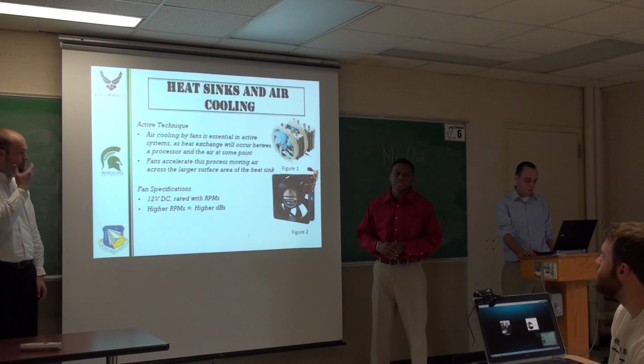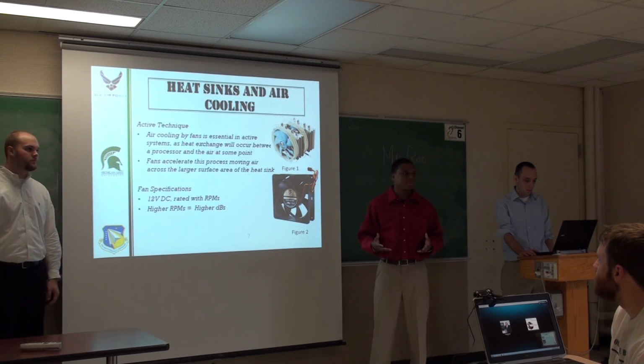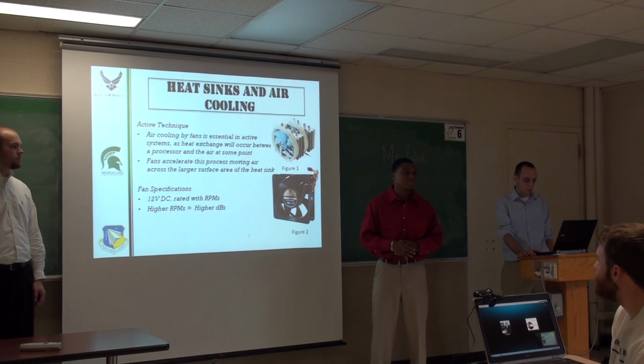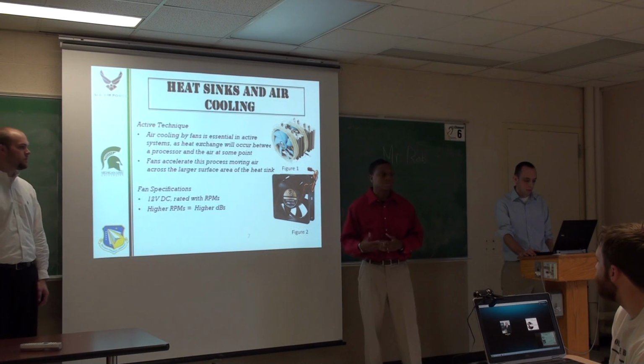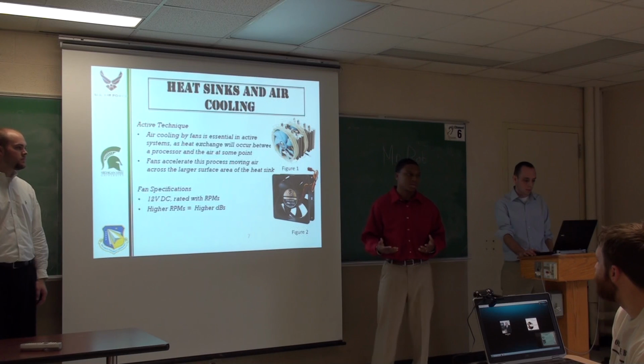Some of the specifications of the fan: they're all 12-volt DC fans, and they're rated with RPMs. The more current you put through the fan, the more RPMs you'll have. So if you need a higher airflow rate, or CFMs, that brings on higher decibels, so it's going to be a louder fan.